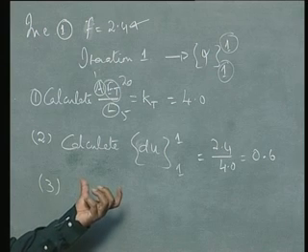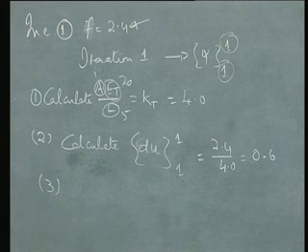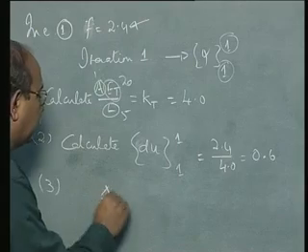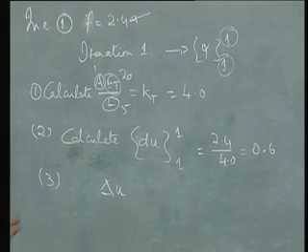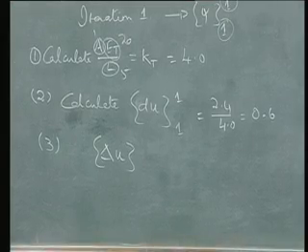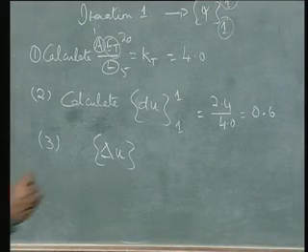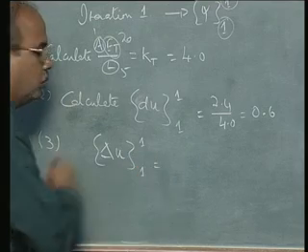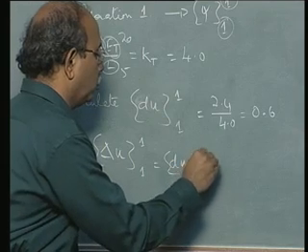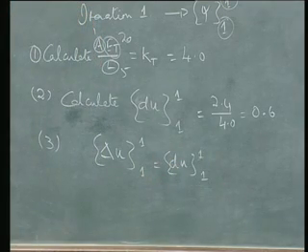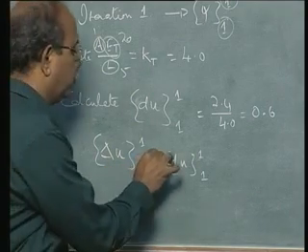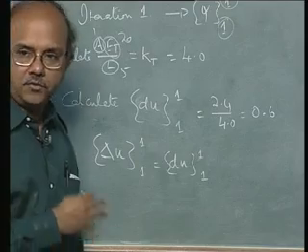In this case, total displacement means the total displacement from the last increment, which we called delta U, not U. Because it happens to be the first increment as well as the first iteration, we have that equal to du 11, or else I have to sum them and put a sigma here. We will do that in the next iteration.